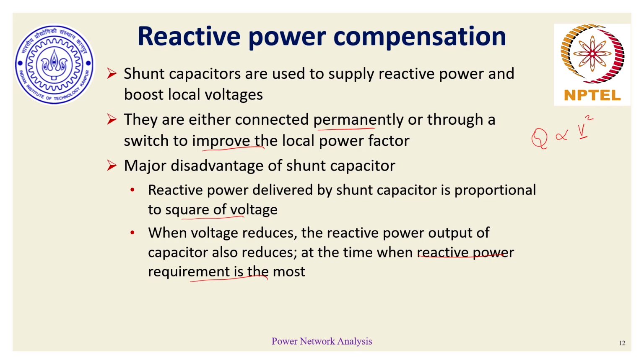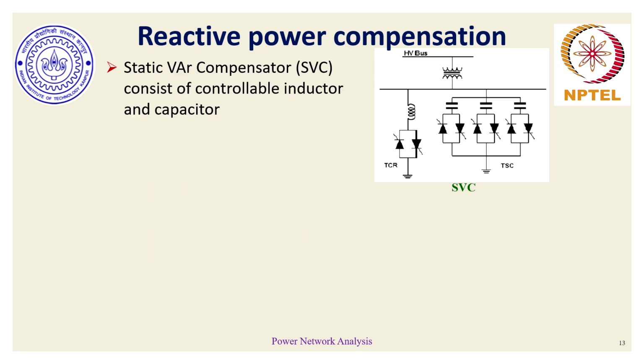So in order to get rid of these disadvantages with fixed or non-switchable devices, comes the concept of static var compensators, which essentially consist of various controllable inductors and capacitors. The inductors are called TCRs.